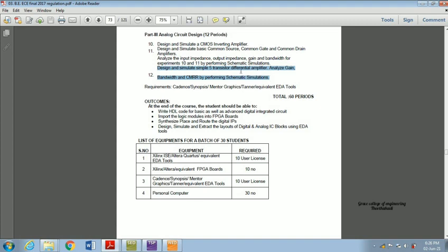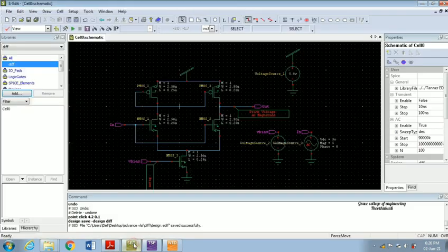For this differential amplifier, we are going to first draw the common mode, which means only a single input has to be provided. Here, as a single-ended input, both our NMOS at the down section are connected together with our single input N in. The output has to be taken from the single-ended mode, not the double-ended, that is, balanced output. So this is our unbalanced output. Since it is a 5 transistor differential amplifier, we have to take the output from the unbalanced one.